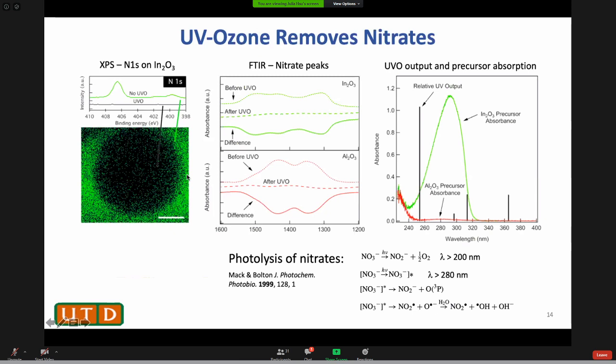dielectric we didn't. The consequence is, to make a pattern with the indium oxide, we only need 10 minutes. For the aluminum oxide, we need 40 minutes, okay? So here I just show you the schematic and the picture before. Here is to show you the transistor behavior, and we got high mobilities. And here is a flexible transistor with good behavior in the ID-VD, okay?